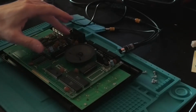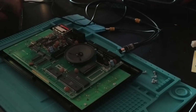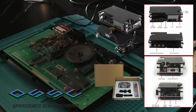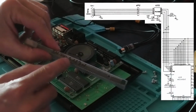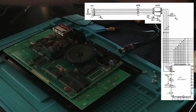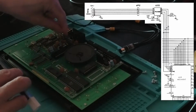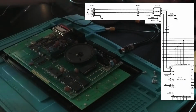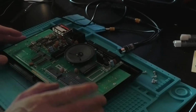Originally I thought that the machine did not have any display at all, because I was connected to my OSSC, which was showing a black output. So I thought that the 74LS365, which does the video output, was damaged. But no, it's because it was in 60 Hz. When plugged into this TV, I see the result.